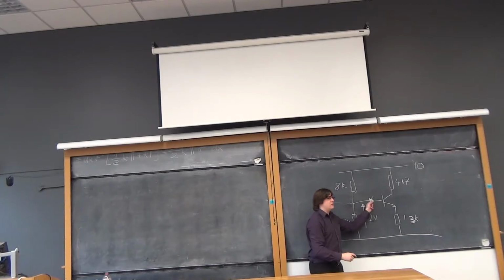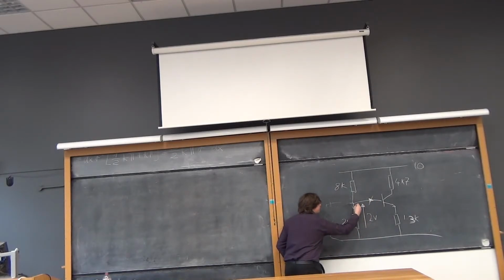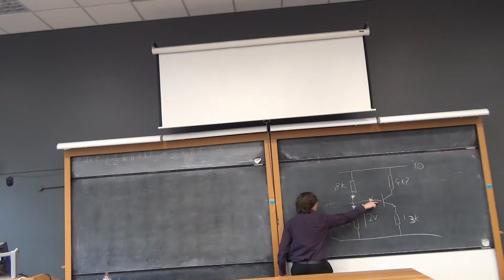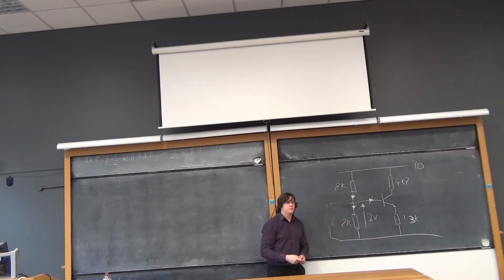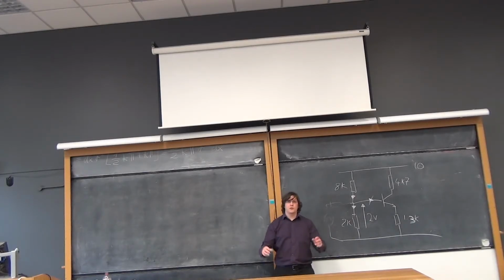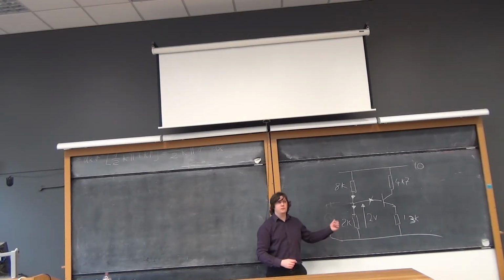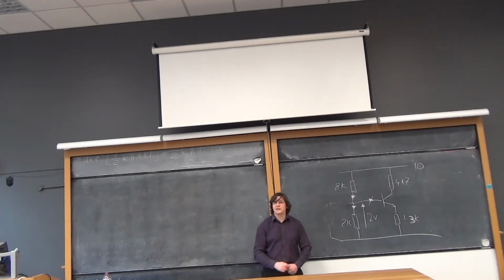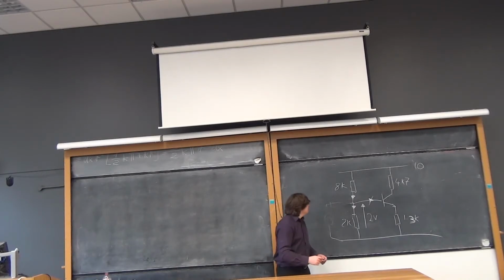There is no current going off down there, because we've got a current here and a current here, and if you want to call this a potential divider of these two, you must say that this current and this current are equal, and there isn't any going off down there. So we're saying the base current is negligible, and if you look at the problem sheets and the exam questions, oftentimes I'll say something leading like state all your assumptions. That one should be on your list of stated assumptions, unless of course you're feeling really brave and you're going to include it anyway, just devil may care.